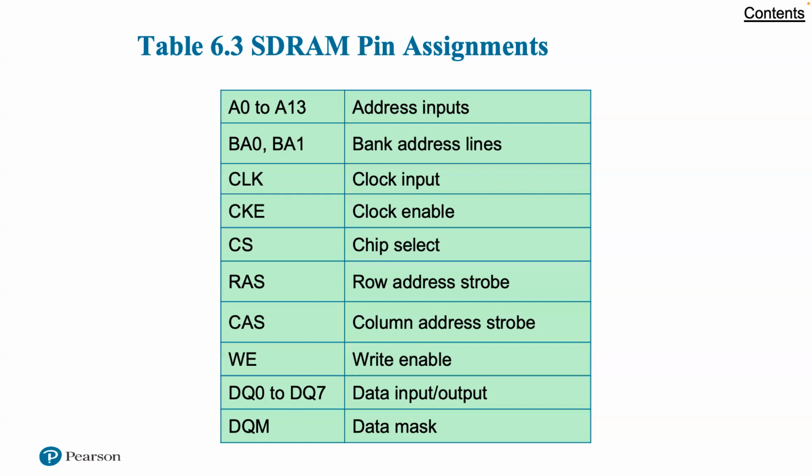The register also allows the programmer to adjust the latency between receipt of a read request and beginning of a data transfer. The SDRAM performs best when it is transferring large blocks of data serially, such as in applications like word processing, spreadsheets, and multimedia.